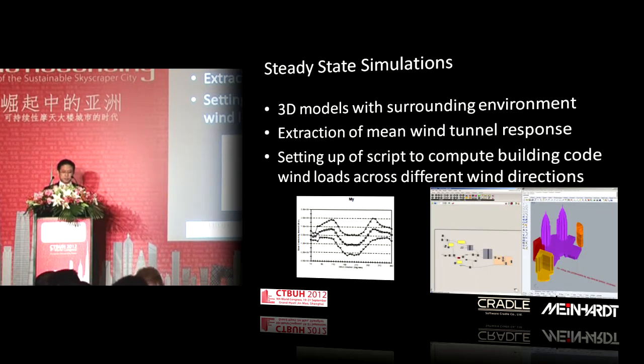So the first thing I'll take you through is the steady state simulations that we did. Those 3D models with the surrounding environment. What we had to do was extract out the mean wind tunnel response. So that would be that middle line that you might be familiar with. And we wanted to compare 3 things. We wanted to compare the wind tunnel loads, the prediction of the wind tunnel loads from CFD, and also the